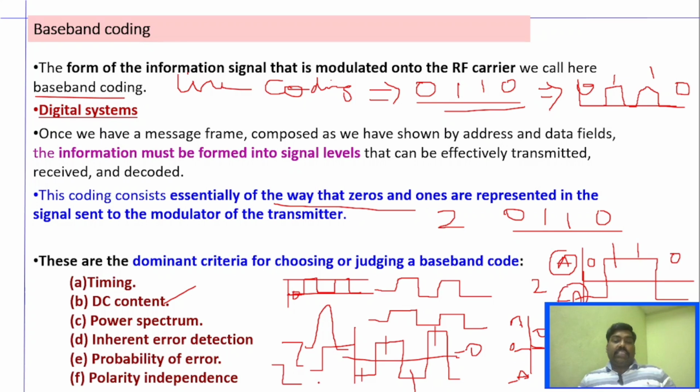And if it is from 0 to 1, right, then the receiver should understand that there is some error, right? And say, for example, you have another coding technique where in biphase level, you will have a transition at every bit. So here, in this particular biphase level, you have a good error detection technique. That's because every bit will have a transition at the beginning.